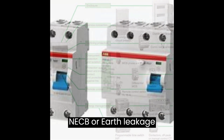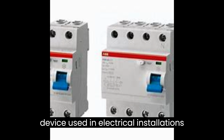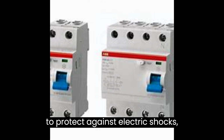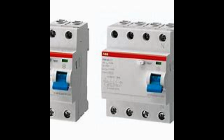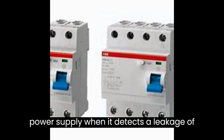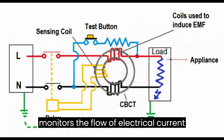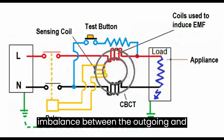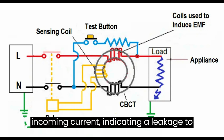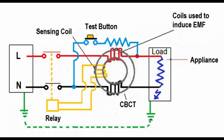An ELCB, or Earth Leakage Circuit Breaker, is a type of safety device used in electrical installations to protect against electric shocks, electrical fires, and electrocution. It functions by quickly disconnecting the power supply when it detects a leakage of current to earth. An ELCB monitors the flow of electrical current in a circuit. If it detects an imbalance between the outgoing and incoming current, indicating a leakage to the ground, it quickly disconnects the circuit, thus preventing potential harm.